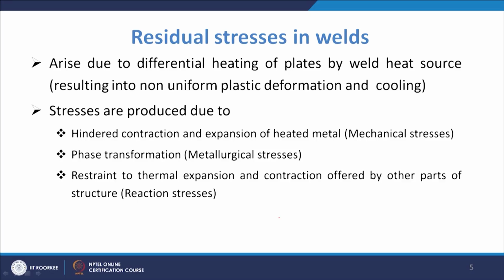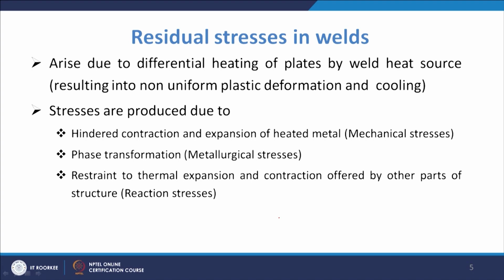Residual stresses in welding arise due to the differential heating of plates by the weld heat source. That results in non-uniform plastic deformation and cooling. It is produced because of hindered contraction and expansion of the heated metal. This is known as the mechanical stresses.